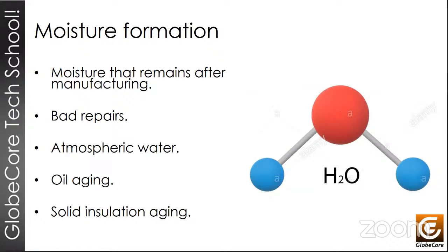One way of contaminating a transformer with moisture is through leaks, because this happens when there is an opening or leak in the transformer, and we can see moisture come into the transformer when there is an oil leak. A transformer is a breathing machine, so when the load increases, the temperature also increases, and this pushes out the air and causes the metals to expand, and at this point we will see oil coming out of the transformer. But when the transformer cools down and the metals cool down, this will cause compression and negative pressure, and the gases from the environment will be sucked into the transformer, and they will contain moisture and other things we don't want in the transformer.